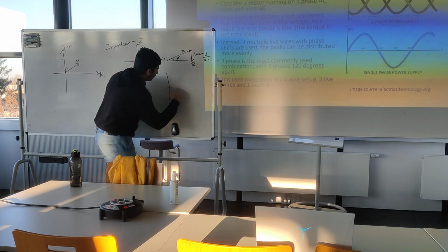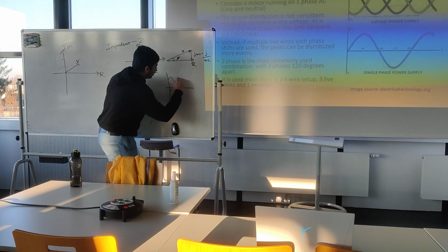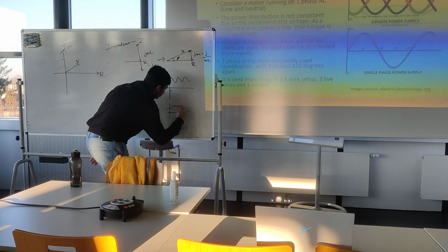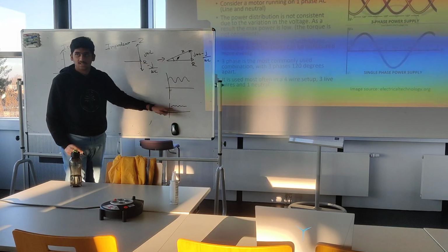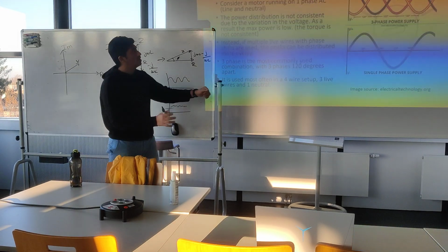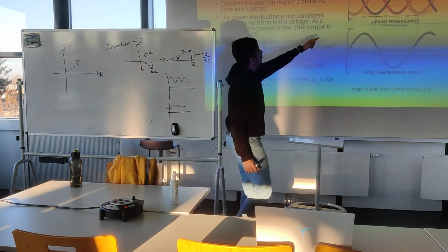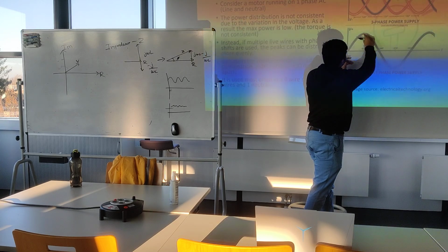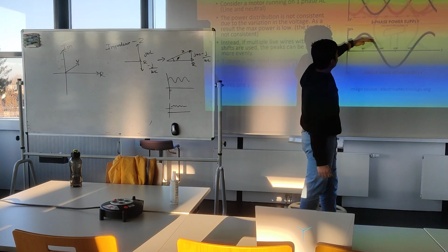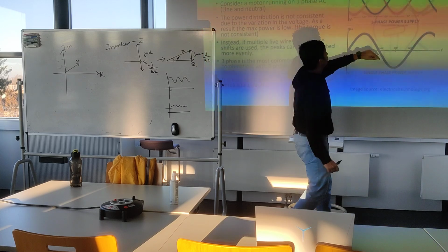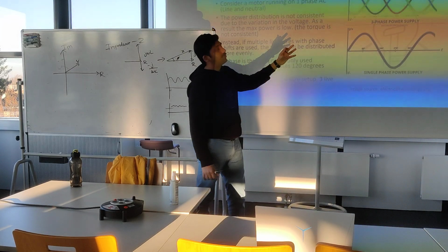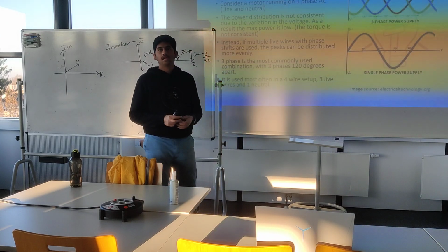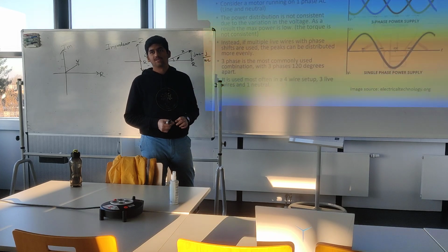So if you normally have torque like this, with three phase you would be getting it like this. So it's more consistent. And also in the same space you can get more power because instead of this, if you do an RMS of this, it will be lower compared to the overall RMS of these three. So you can get more power as well if you use three phase. That's why most powerful equipment, AC motors, will have a three-phase power supply.